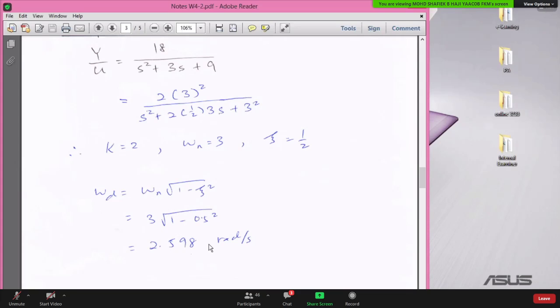Why is that? Because we have a damping ratio here. We have a damper here, and it is going to modify slightly the natural frequency. The natural frequency is when the damping ratio is 0. But with the presence of damping ratio here, the actual frequency of oscillation is going to vary slightly. So the computation of the actual frequency, which is omega d, is just omega n multiplied by square root of 1 minus zeta squared. So that is your three parameters.